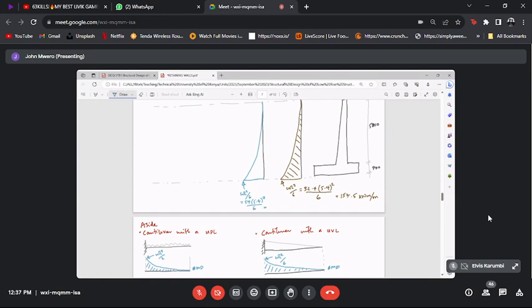This will be 262.4. Again, kilonewton meters per meter means every meter width strip of that wall has to carry 262.4 kilonewton meters courtesy of the water that is retained by that wall.